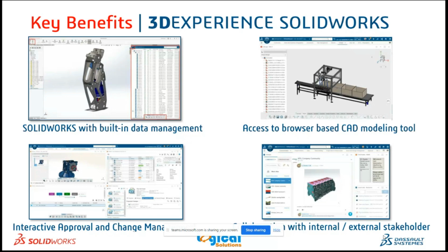And interactive approval and change management. As I said, SolidWorks 3D Experience acts as a basic PLM. We can change our approval stages as in PLM, and we can also change different maturity states. We can release the drawings, or freeze the drawings, or revert back into the in-work stage. Automatically, the user who is assigned the task will get notified. Okay,